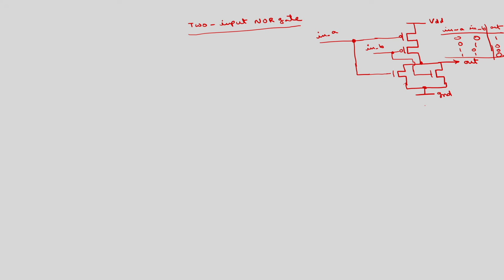Okay. So, in ideal case, if a device is on, we will take this as a short circuit, otherwise open circuit. We can verify in the similar manner. Okay. Now, if I take the Verilog code corresponding to this one, we will call this one as P1, P2, similar to NAND operation. This is N1, N2. So, module I will call as CMOS NAND NOR. We have only one output and two inputs.